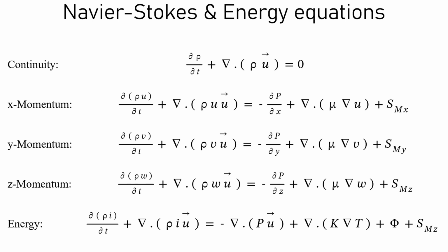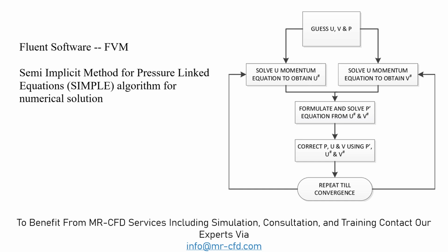And for the final term, you can see that this term is designated by S and represents the source terms. Now this source term can be replaced by different forces based on your project. And for the energy equation, we're going to explain this equation in the next session where we simulate the heat transfer inside a heat exchanger.